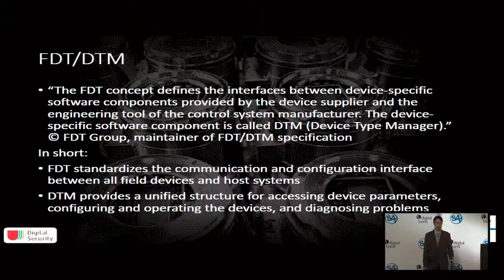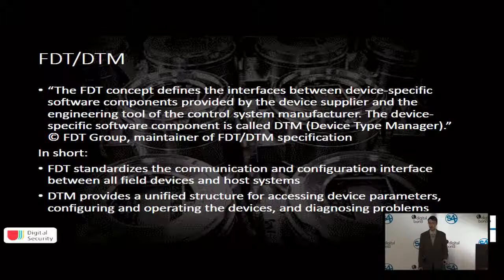For example, in every ICS infrastructure, you have thousands of low-level field devices. How do you manage them? Because most of these devices, despite working on traditional industrial protocols, have different application layers and different vendor-specific commands. And how do you handle them? One solution is DDL or EDDL, and the other solution could be FDT DTM.